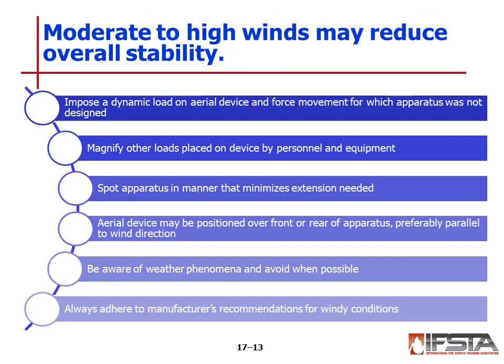Moderate to high winds impose a dynamic load on the aerial device, which may reduce the overall stability by forcing movement for which the apparatus was not designed. Movement by wind also magnifies other loads placed on the device by personnel and equipment.